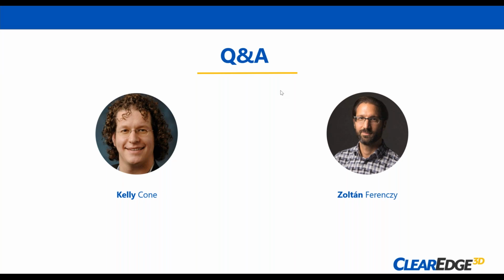Absolutely, yeah. I've actually done this workflow with a laptop out next to a job site at 5 in the morning when they're pouring concrete, and you typically want to have the computer there next to the laser scanner, because it doesn't make a lot of sense to be kind of off the site, since you'll be doing the scanning, analyzing, telling the people where to refinish the high spots and low spots, scanning again, analyzing, and then repeating that process as many times as you need while the concrete is still workable, until the floor comes within tolerance of your elevations.